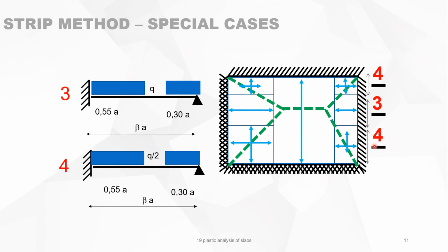For strip number 4, or section number 4, you see here the double arrow. Half of it is carried in this way, which we already got in the cross section running in the vertical sense, that we already took. And now only what's left is half of it, so half in this direction and half in this direction. That's why it's Q over 2.